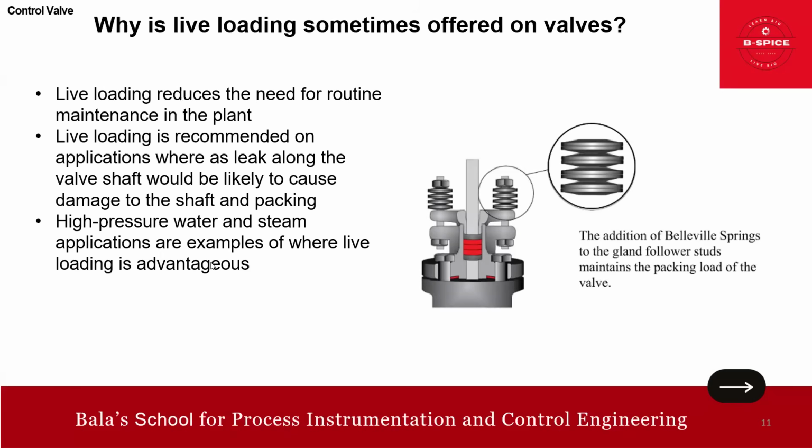Now, very interesting. Why is live loading sometimes offered on valves? You see here, friends, this is the packing, right? You have this live loading. The addition of Belleville springs, here, to the gland follower studs maintains the packing load of the valve. Live loading reduces the need for routine maintenance. That's the point. Live loading is recommended on applications where a leak along the valve shaft would likely cause damage to the shaft and packing.